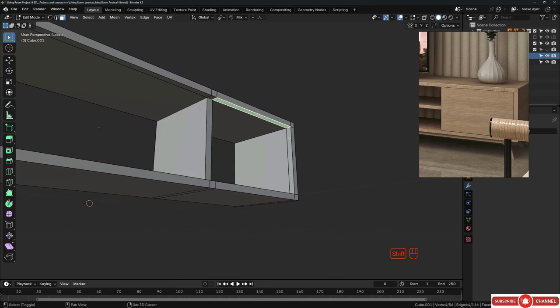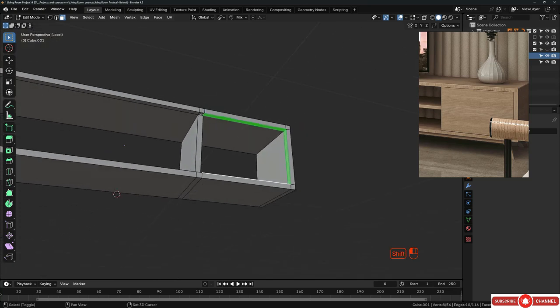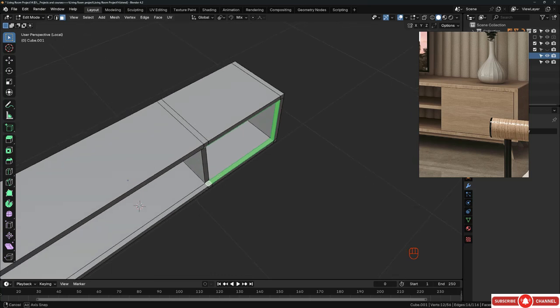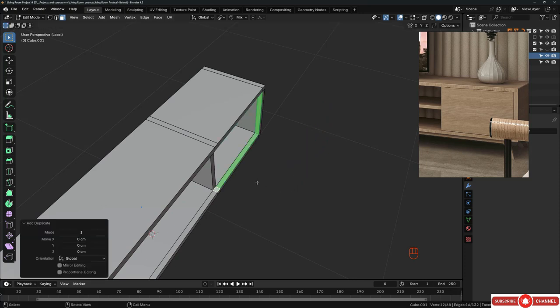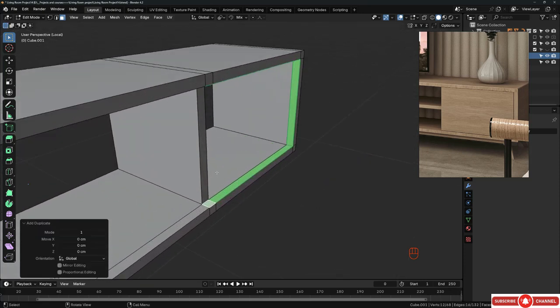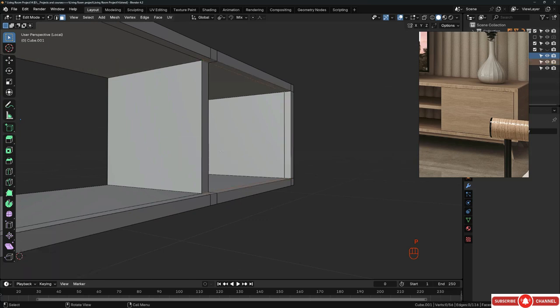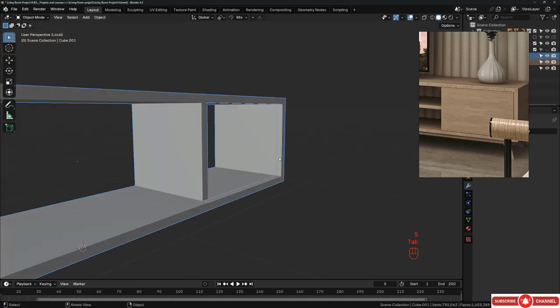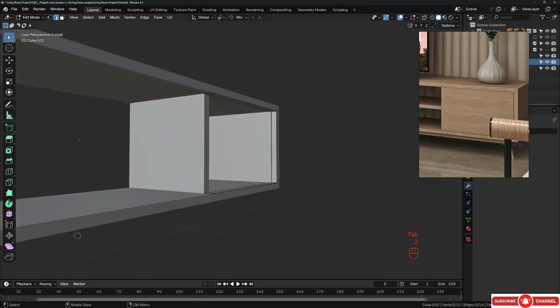All right, now I will select the three faces like that, and I will add this with this one, and I will hit Shift D to take a copy like that, and I will hit right click to leave the copy in the same place, and I will detach it. Just hit P and then S, tab out, and now let's select this new piece, and I will tab to the edit mode of this piece.